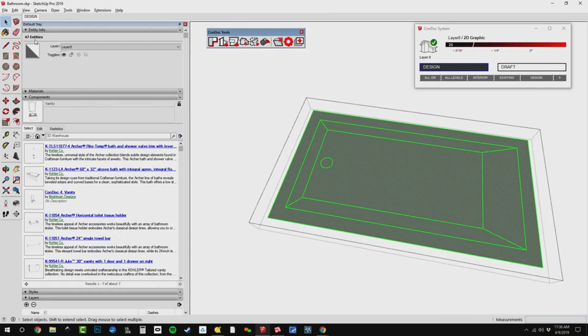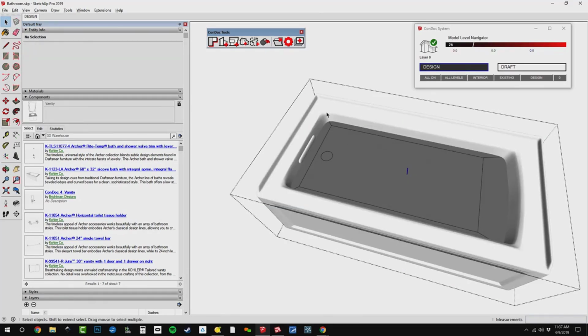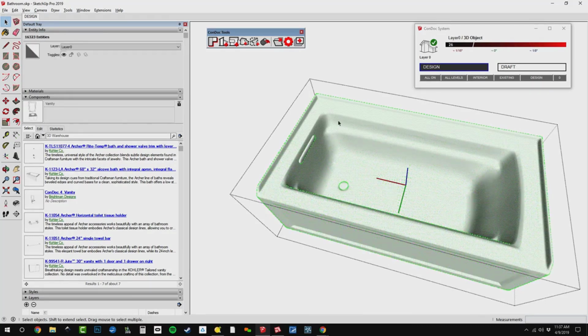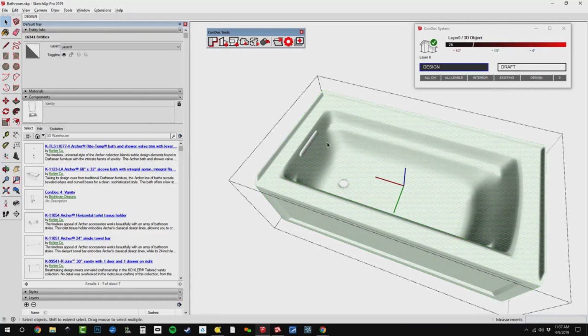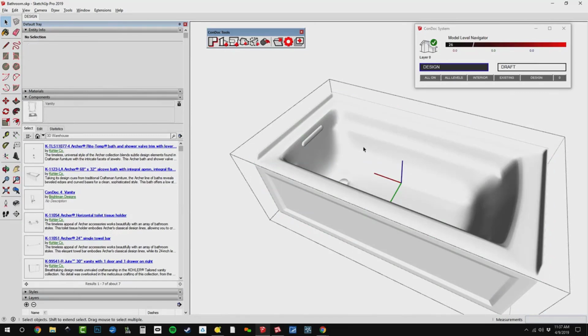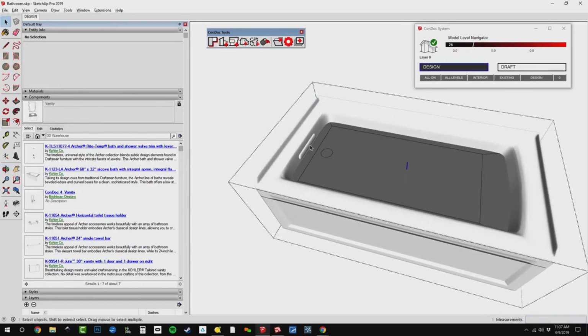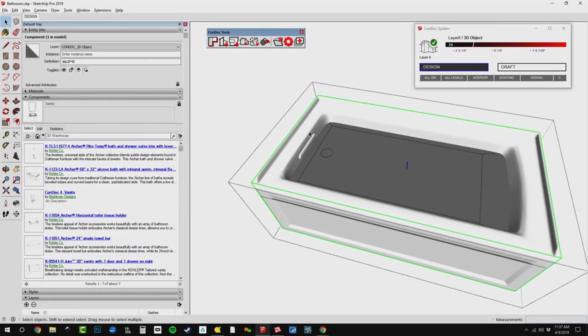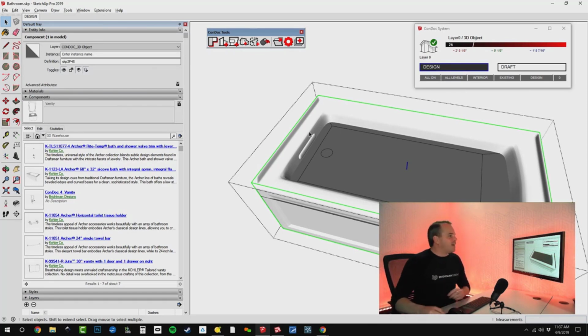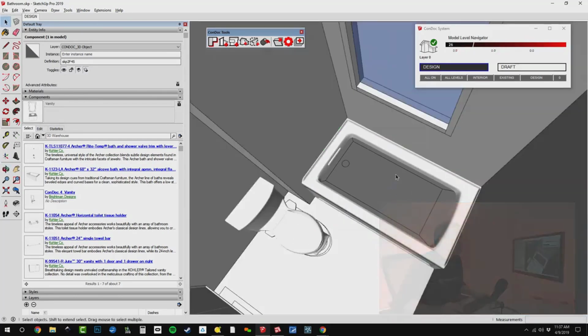Now, take a look at this. There are 47 entities that compose the 2D graphic. There are 40,000 entities, if I hit Control A, that compose our 3D object. All right. So what that means is that when we send this to Layout and when it gets flattened, we're flattening the 47 or whatever it was. So we are taking the load off of Layout, making it a much lighter weight model, and that's what you want to keep in mind.